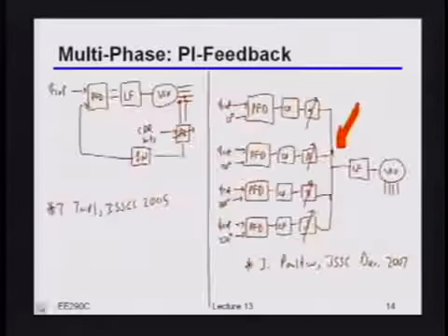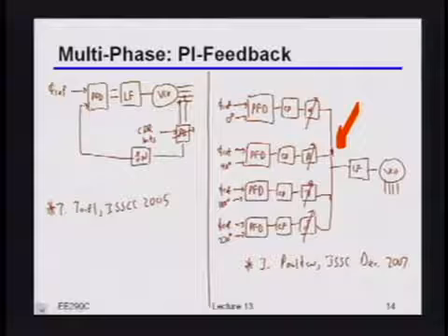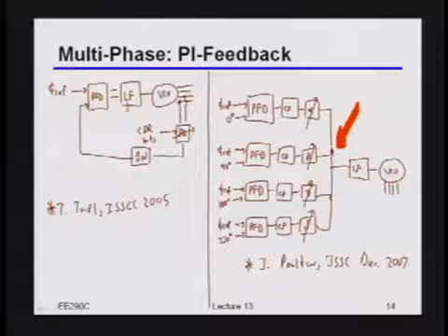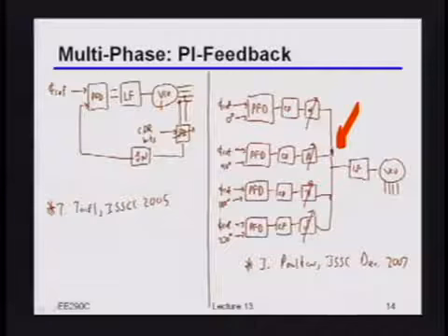Follow-up question. If you compare the two of them, I guess a good trade-off is the first one? Yeah, this is a pretty reasonable thing to do. You have to work out exactly what context you're in, how much multiplication you need, and what the reference is. But this is indeed a fairly reasonable approach as well, and people are using these kinds of things. Although, again, it's heavily dependent upon how much multiplexing you're doing in the first place. If you're not doing very heavy multiplexing, for example, if you have a full rate system, then there's no difference between doing this and just having the phase interpolator open loop to begin with.